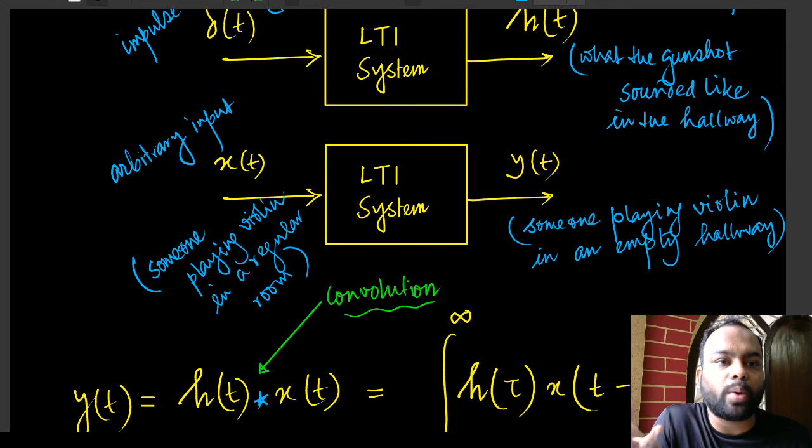And again, somebody is asking, how can we figure out whether a system is LTI or not? We have to separately check for linearity and time invariance. Linearity has two constraints: it must support the scaling property and the superposition property. So if a system satisfies the scaling property, the superposition property and the time invariance property, then the system is linear time invariant.